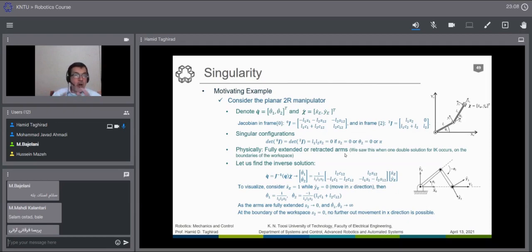So this relation always exists. And this collaboration that we have between differential kinematics and inverse kinematics can reveal very important facts. But the important thing is the Jacobian is a matrix, and we can work with that quite easily. It is much more effective to work on the matrix and on the inverse of the matrix rather than finding the double solution of the inverse kinematic map, which was computationally extensive. So the Jacobian is very important, as you see here.